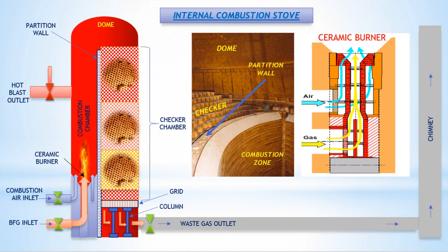Dome encloses the combustion zone. The dome contains the fuel-air mixture and combustion process, maintaining a consistent temperature. Directs heat flow. The dome's shape helps direct heat from the combustion zone towards the regenerator.